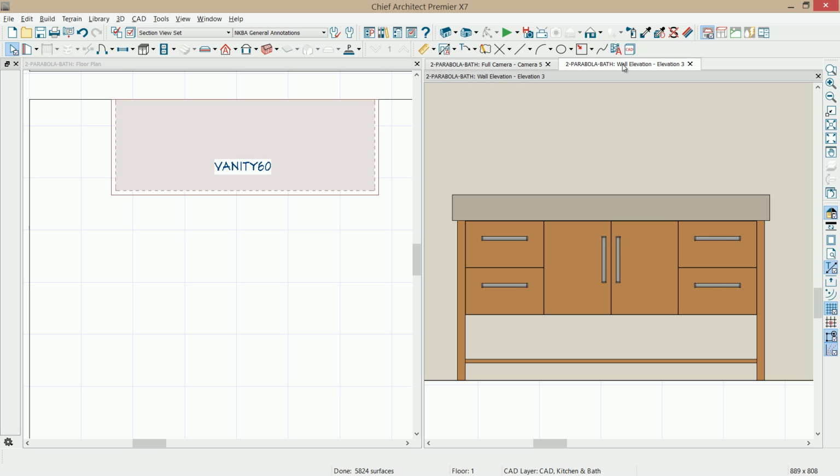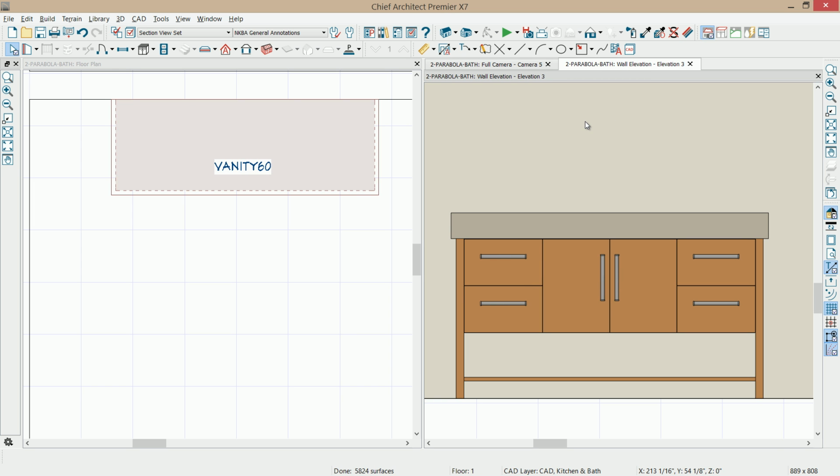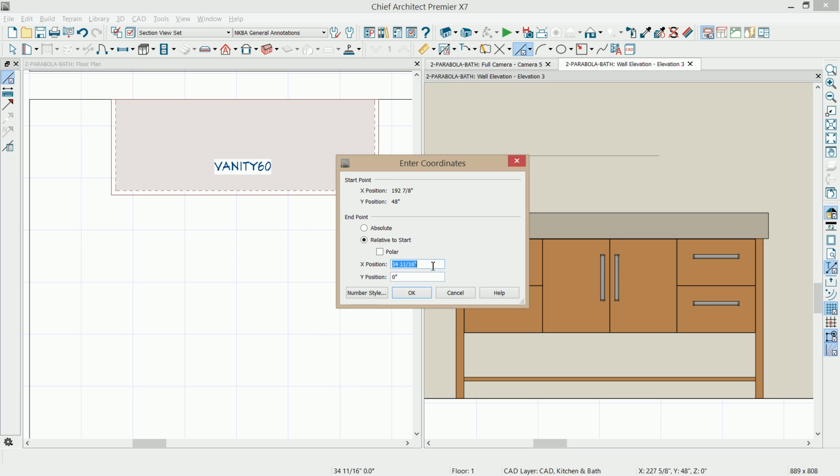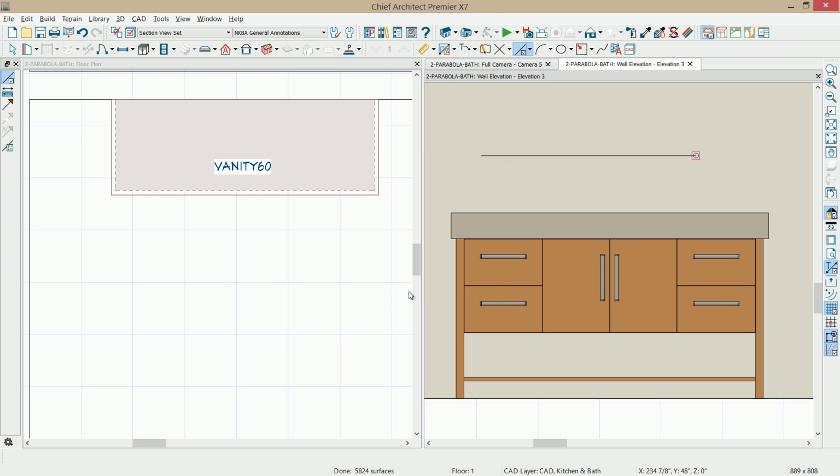And my basic dimensions for my sink are going to be 42 inches by 15 inches. And here's what I'm going to do. I'm going to start with a line tool, and I'm going to draw a line. Again, I'm going to use the tab key. So I'm drawing out that line. I want it to be 42 inches. That's going to be the length of the sink. And I'm not going to worry about centering it on the cabinet at this point. I have the 42-inch length here.